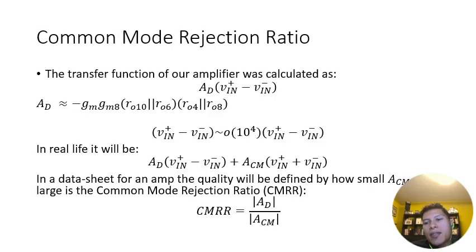In this particular class, I stopped going over this, but in your lab, you will build an operational amplifier circuit. That circuit will have a gain that is approximately 10 to the fourth. So for that kind of circuit, you can get about a gain of 50 and still assume ideality. If you go to a gain of 500, you're going to start very clearly seeing the deviations from ideality.